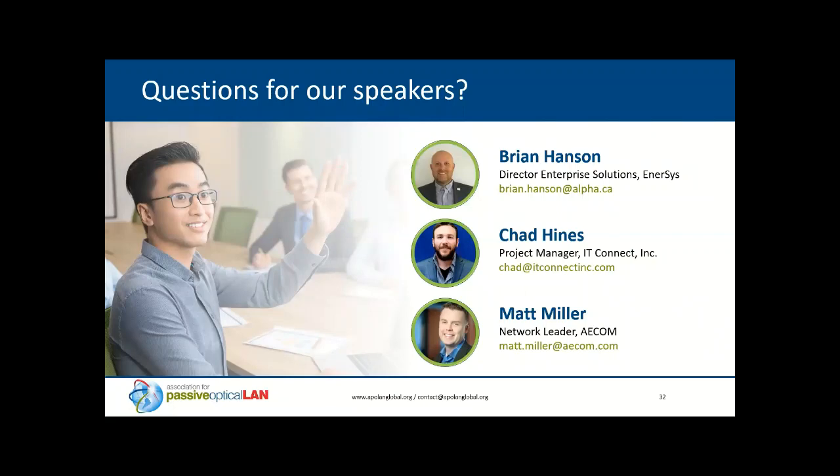Yeah, we get that question a lot because we do have an acronym problem in this industry. So GPON is a specific standard of PON technology. There are multiple standards bodies out there, but GPON is the most widely adopted one and one that we hear people refer to this technology as. PON refers to the technology as a whole, whether that's for fiber to the home, fiber to the edge, or for passive optical LAN, which is the specific application of that technology in the LAN environment, so POL.